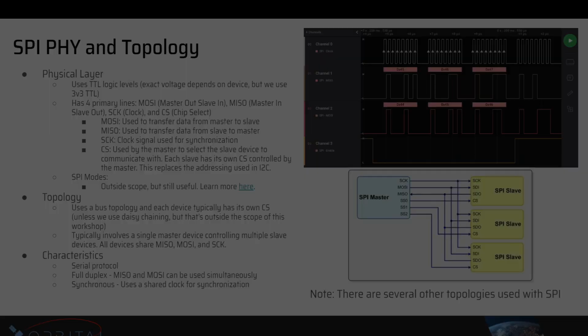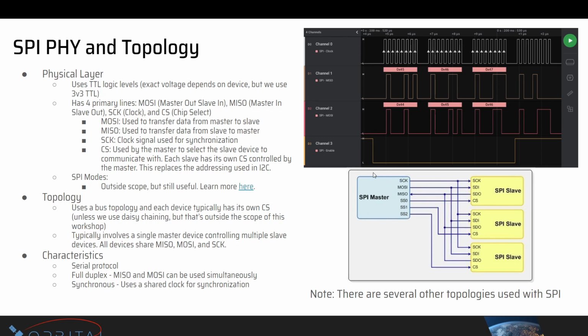It depends on the MCU you're using for the master. You can have as many slaves as you have chip select lines. Like the RM46 has 5 different SPI buses, and each of them has chip selects 0 to 4, I'm pretty sure, maybe 0 to 5. So that would only be able to have 5 SPI slaves.